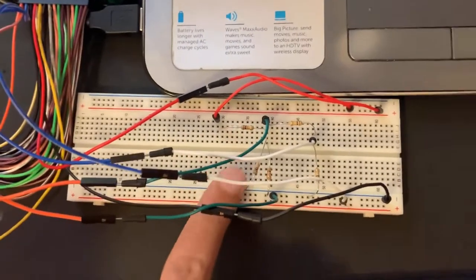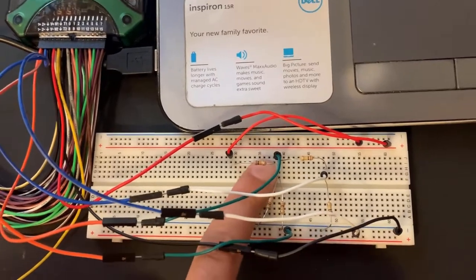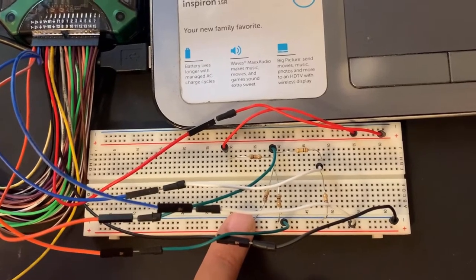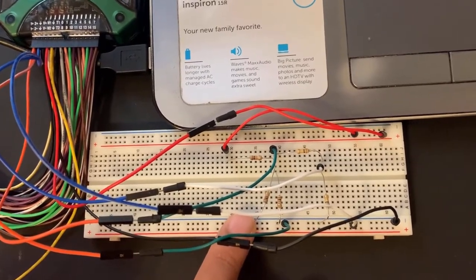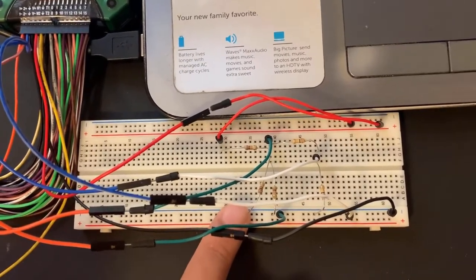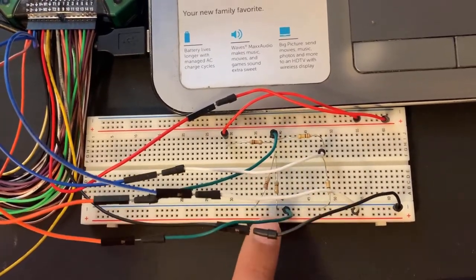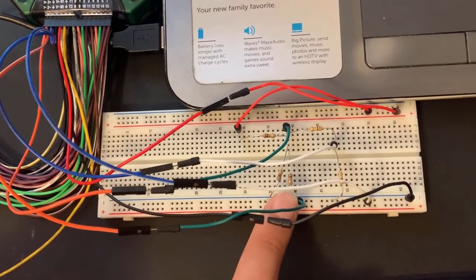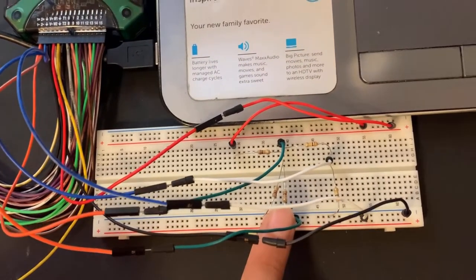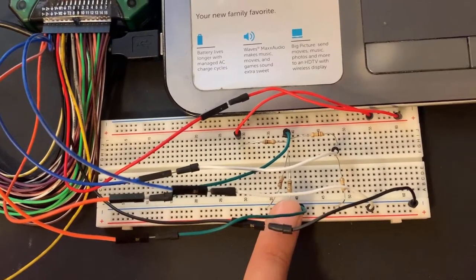The power over R2, we apply the same relation for all the resistances. It will be equal to V1 times the current flowing through the same resistance. So V1 is equal to 0.416 times I1, which is equal to 0.416. It will give you 0.173 milliwatts. R3 here will also have V1, since the drop over the other resistance is the same. It will be 0.416 times I2, which is equal to 0.0416 milliamperes. If you multiply them, you get 17.3 microwatts.